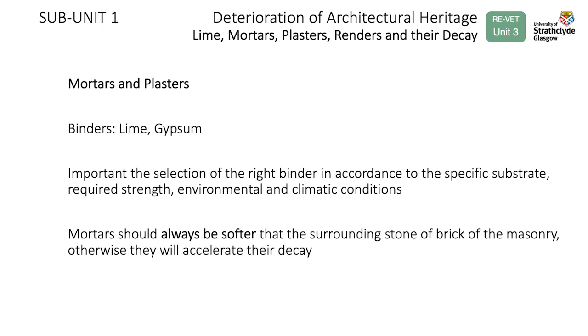The selection of the right binder is important and has to be made in accordance to the specific substrate, required strength, environmental and climatic conditions. Mortars should always be softer than the surrounding stone or brick of the masonry, otherwise they will accelerate their decay.